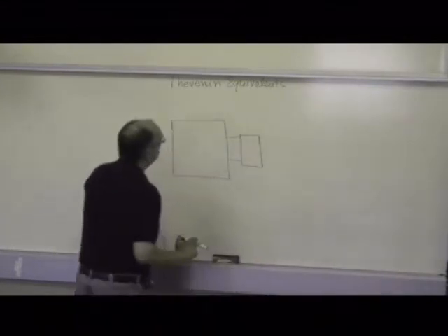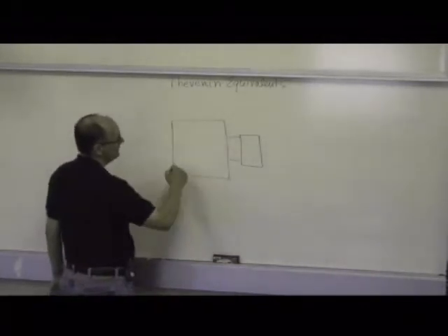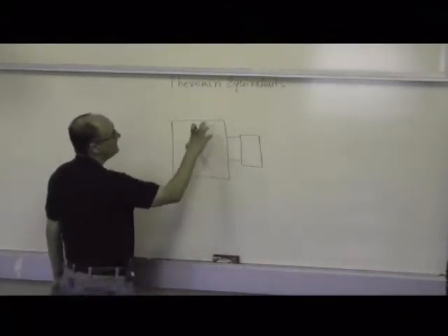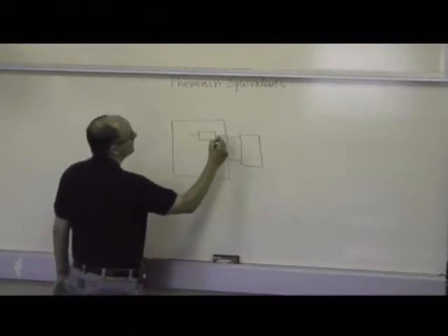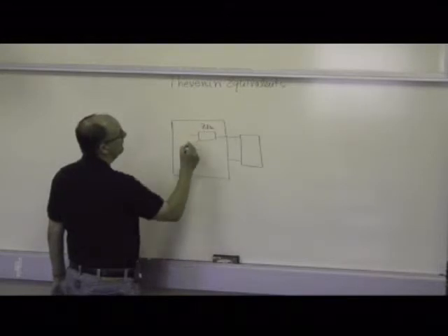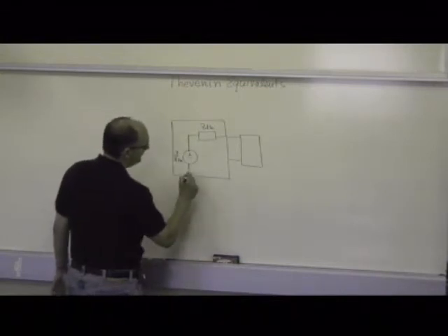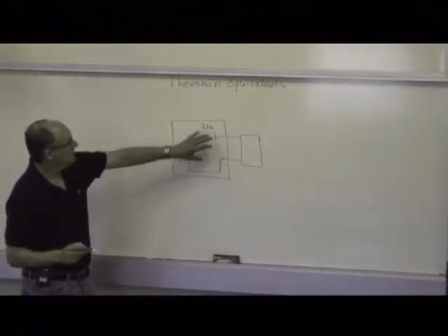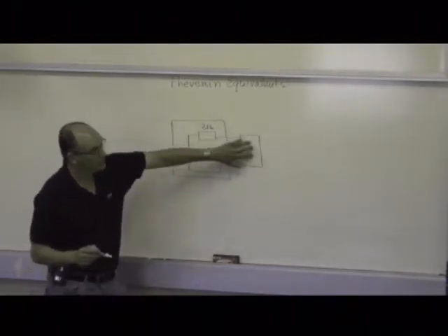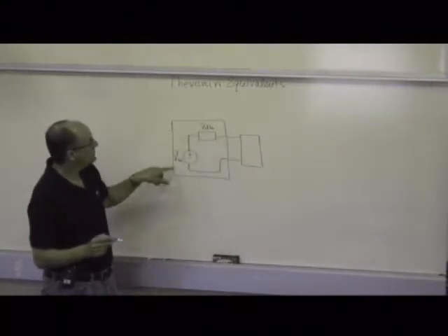And Thevenin equivalents would let you do something like that because they would represent, in theory at least, the entire network with an equivalent impedance, which we label Z Thevenin, and an equivalent voltage source, V Thevenin. And that then simplifies the circuit dramatically because you have only two elements and you can model this in much greater detail, not worrying about how many nodes were in here.